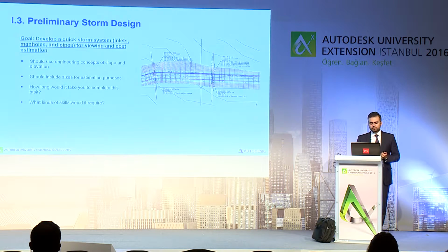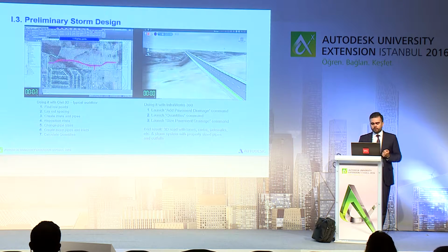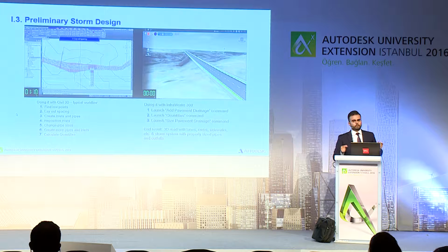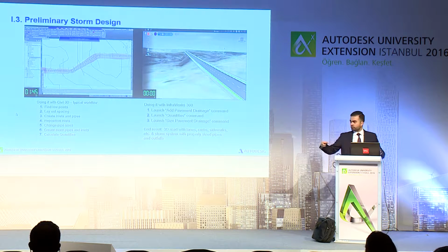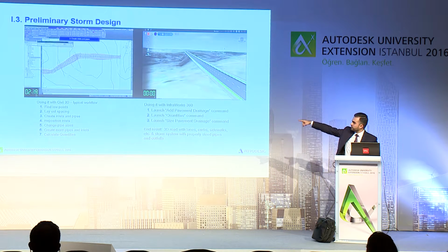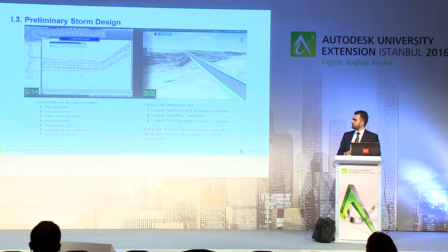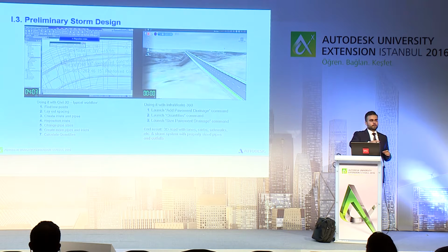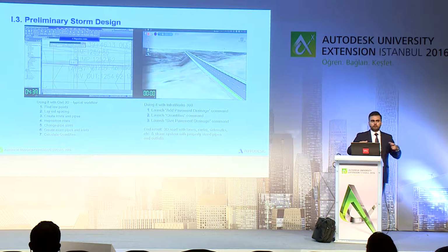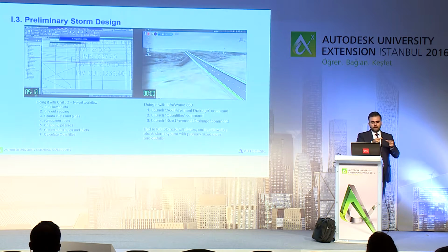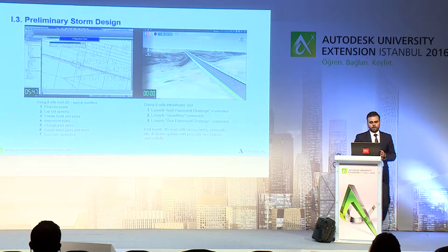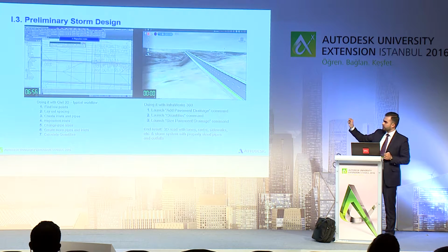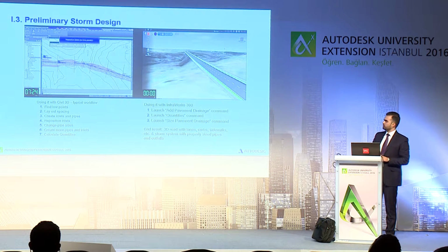The third one is storm design. And here we do have certain challenges. Those of you who design storm drainage networks for any road, like we're seeing there using Civil 3D, know it's a pretty tedious job because the designer himself has to place each and every structure, like an inlet or a manhole, and align them with the road with a certain slope.